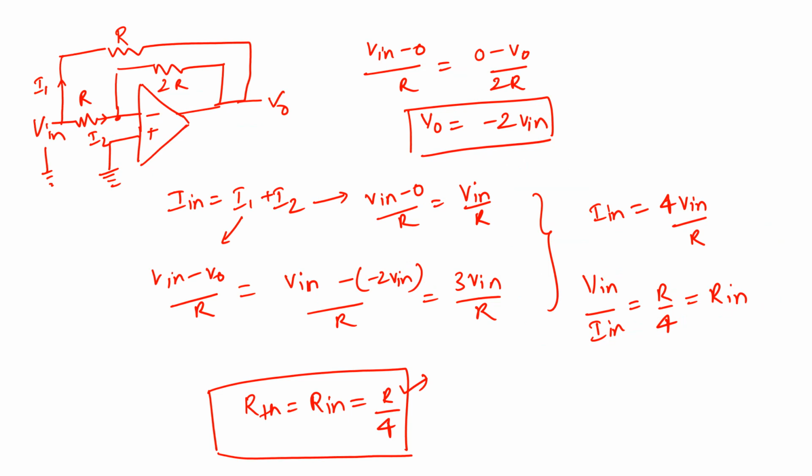Op amps are amplifiers, so amplifiers need to be cascaded to get a higher gain while being stable. So we use negative feedback to make the op amp stable, and to get a higher gain, we cascade stages of op amps. And hence the input resistance is very crucial to know how much loading effect the op amp has on the previous stage of the total amplifier.